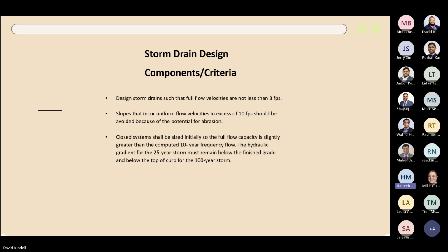Yeah. I mean, the people doing it should know, but typically they give us a video. They drive a little remote control car with a camera inside the pipe, and they give us a video of that, and then they prepare a log saying where the cracks or any deformities are. Someone reviews the footage, checks for defects and notes it in a report. So basically, the project limits is enough information for them to develop their scope.